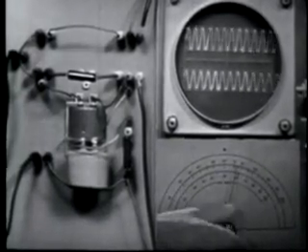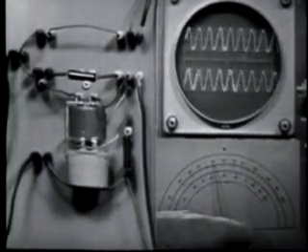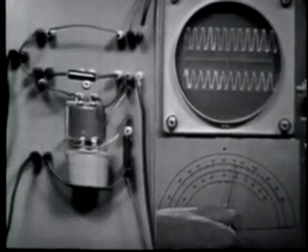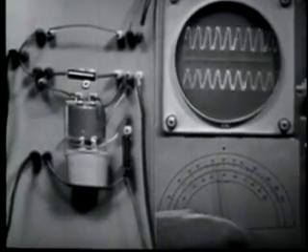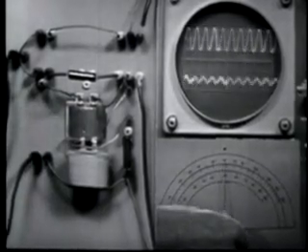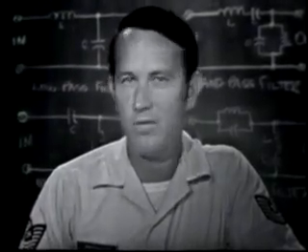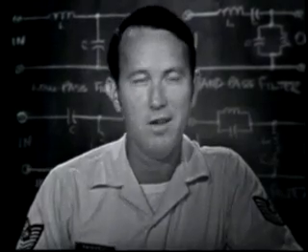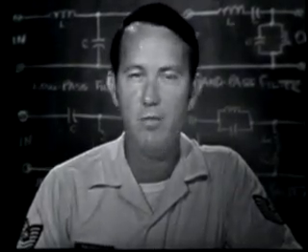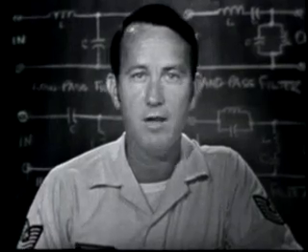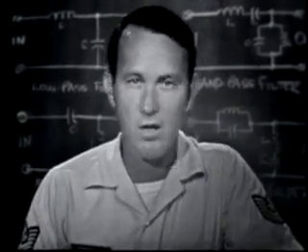At frequencies off resonance, the parallel tank impedance is minimum and passes these frequencies through. The series tank impedance is maximum and develops the output voltage. The circuit is passing frequencies off resonance. And note the extremely sharp response, since we're now using two tank circuits. We've now demonstrated all of the so-called simple filters. Next, we'll discuss modifications that can be made to the basic L section that will improve the overall filtering action by adding additional filter components to the circuit. We'll start out with the basic L section low-pass filter.